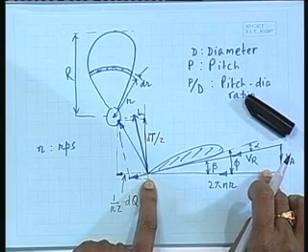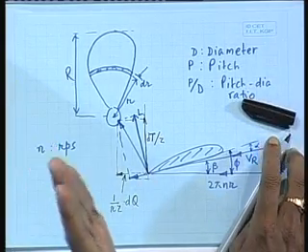Is that clear? So, now you understand, I have got a blade which is twisted slightly and it is rotating in this plane with an angle phi. So, when it is rotating, the tangential velocity in the opposite direction is equal to 2 pi n r, and there is an axial velocity flow past the propeller, because the propeller is moving forward, we are considering the flow in the other direction as V A, that is here. Thus, the resultant flow, instead of being like this, is at a small angle of attack.